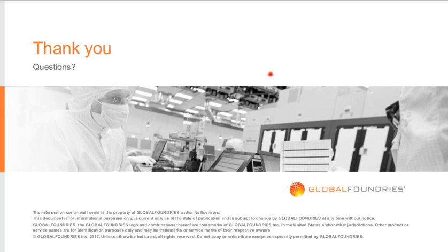For the PA, Fmax is a very important one for this technology. The Rgate is low, and also in the new model, the Rgate is already included in the modeling, so we can have very good model hardware correlation. The Fmax can be higher than 315 gigahertz. So it's very good not only for the Ka band, it is also good for 60 gigahertz, 70 gigahertz design.